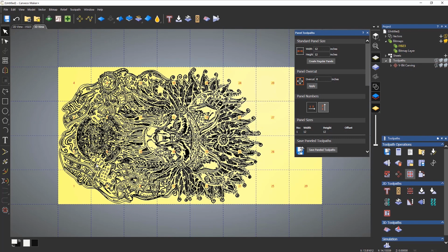Because if I were to machine this like this, I would get little areas that would be, say, the radius of the V-bit carving when it was coming up. Okay, so I may need to overcut this. So that's something to bear in mind when you're doing that.